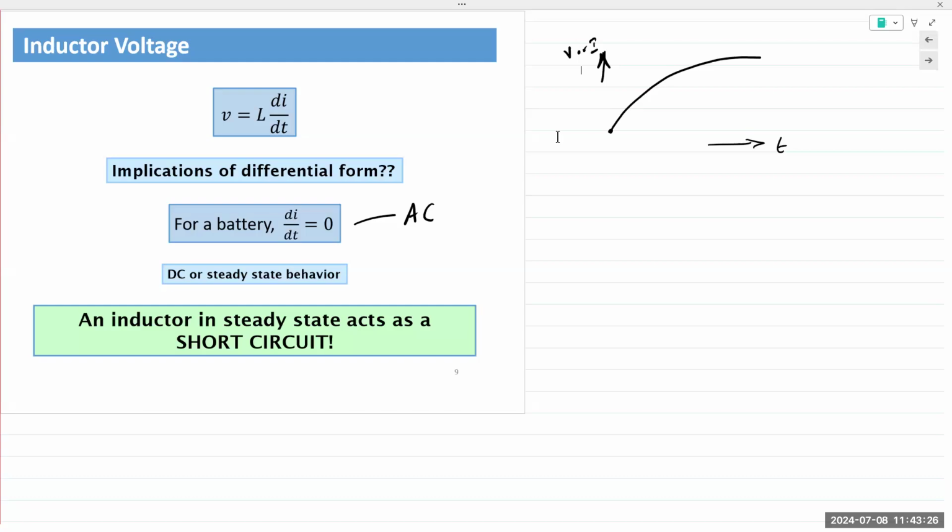Now, what happens is this magnetic field gives rise to an opposing EMF. EMF is another word for voltage, electromotive force. This voltage is opposite to the flow of the current. Now, if you try to change the input current, that magnetic field is going to oppose any change in this incoming current. And when it opposes, it is not direct opposition.